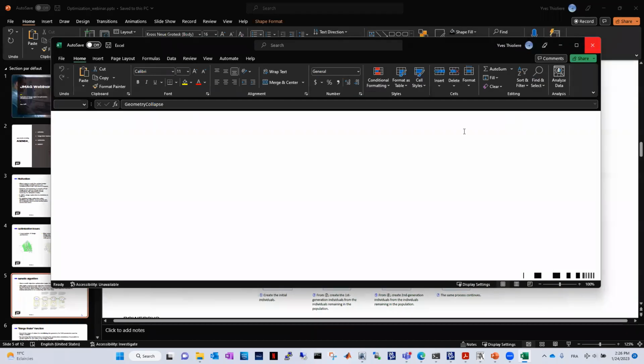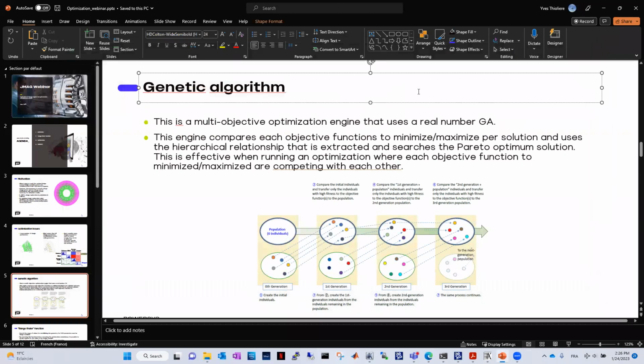But yes, the answer is yes, and that's the predictive model. So predictive model or learning data. JMAG will take some values for the variables, and the CAD will just reply that yes, it's valid, or no, it's not valid. So there are several criteria for that. Like JMAG is checking if there is any region overlapping, how many lines, points are there. If there is less or more, it means that maybe there are some collapsing or something like that.